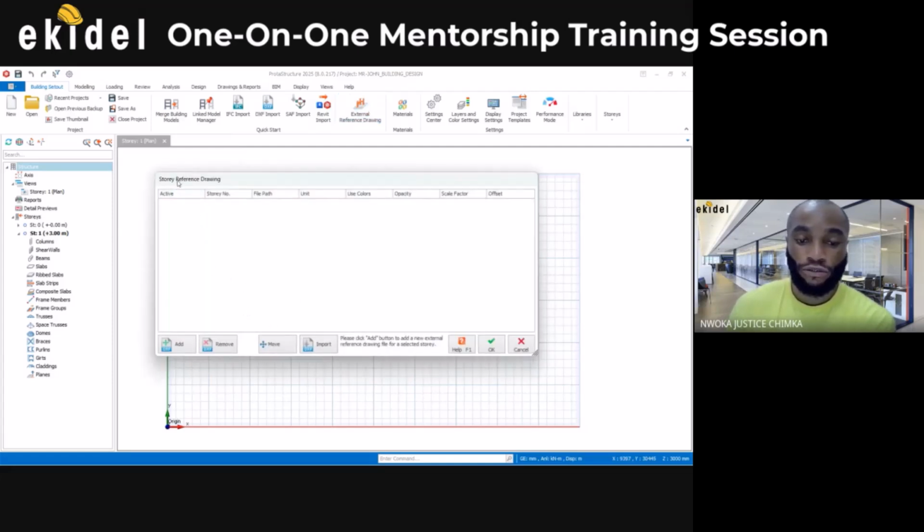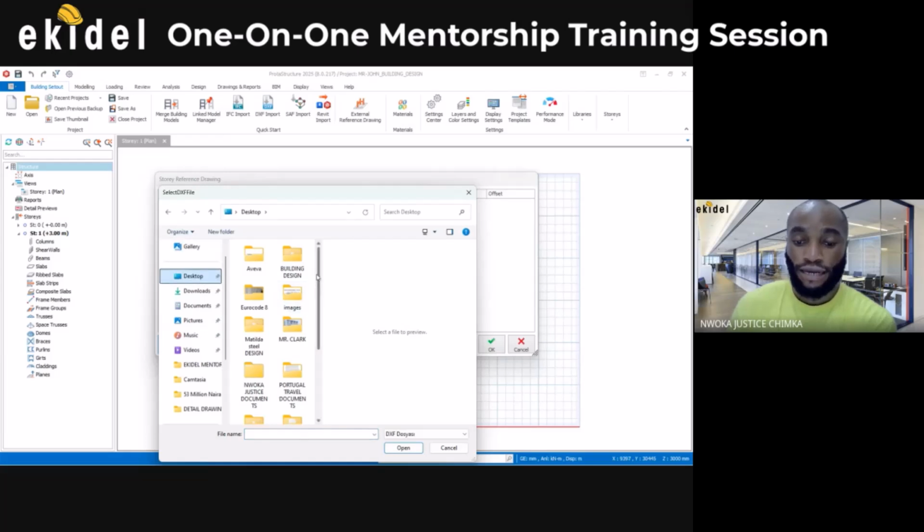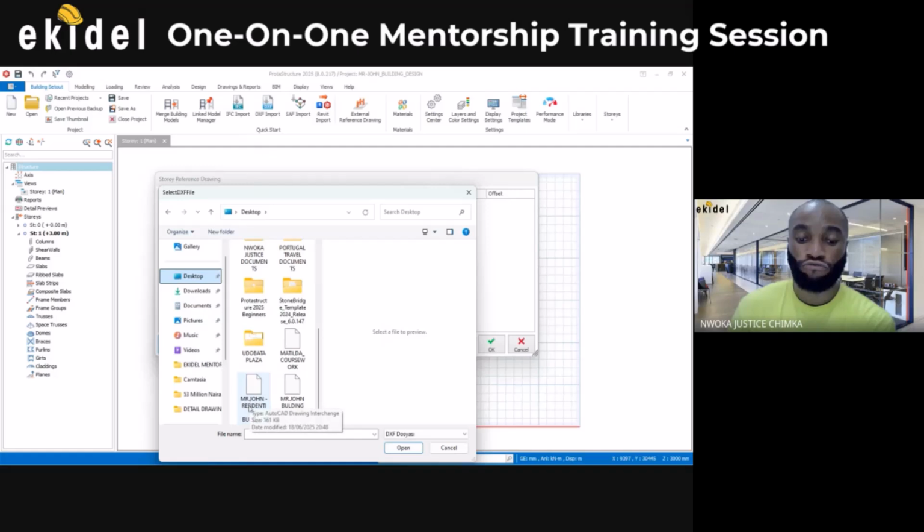Then it will display this dialog box. I'll then click here that says add DSF. I'll click on this place here, and then I have to locate the place where I saved it before, under my desktop. Then I'll scroll down to locate Mr. John's residential building. So I'll click on this and say open.